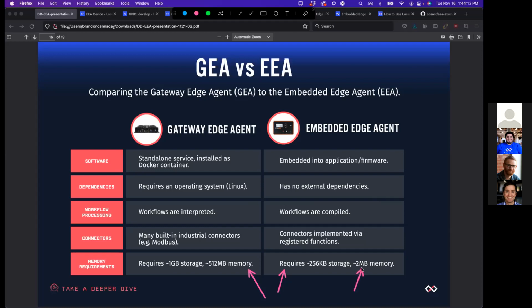And what we've seen is, I think 2 megabytes of memory is very comfortable. I've never seen anything require more than that. On my example with ESP, I'm running about 512K, or a little less than a meg, but 2 megs is really that comfort area. That's because your workflows are going to be 256K at most. You'll need probably 2 copies of that. You'll have one running. You'll need to bring another one in over MQTT. So that's about half a meg already. You bring in the runtime and MQTT, you're going to be up about a meg.